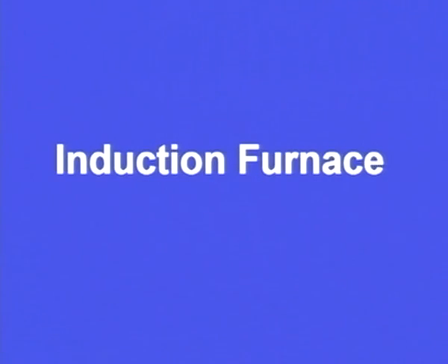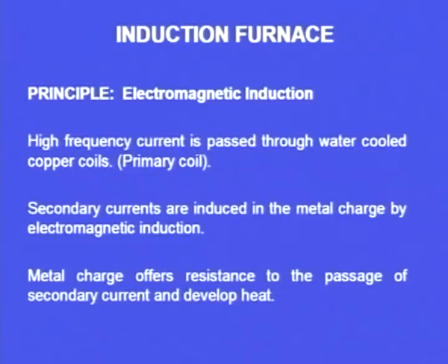Next one, induction furnace. The principle is electromagnetic induction. The furnace works on electromagnetic induction. High frequency current is passed through the water cooled copper coils. So, this copper coil acts as the primary coil, and secondary currents are induced in the metallic charge by electromagnetic induction.